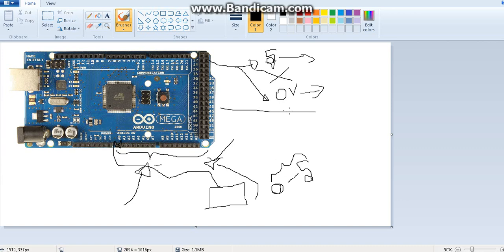But if it is analog, you can give intermediate values. Since we are talking about analog input, we can give any voltage between 0 and 5. 0 is the minimum, 5 is the maximum, because we are going to use sensors or input sources of 0 to 5 volts at most. So when it comes to analog values, any voltage between 0 and 5 can go into the particular pin, and we can read the value. From that we can make some interpretations.